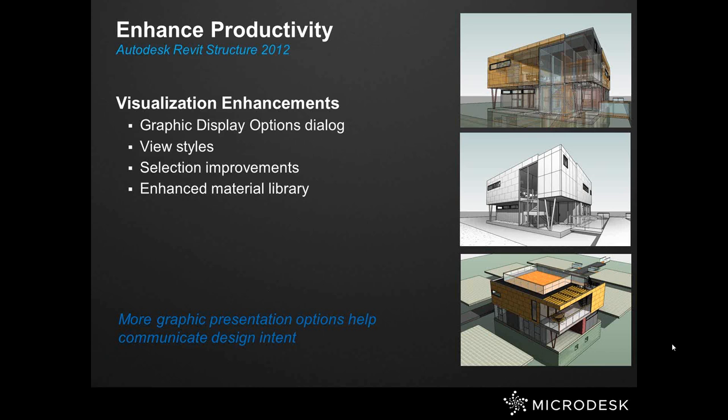Some of the new and enhanced view styles are realistic with edge mode, ambient light and hidden line in consistent colors mode. Shadows are now available in consistent colors mode. And ghosted surfaces, which displays all surfaces with a 30% transparency, is now available in all view styles.